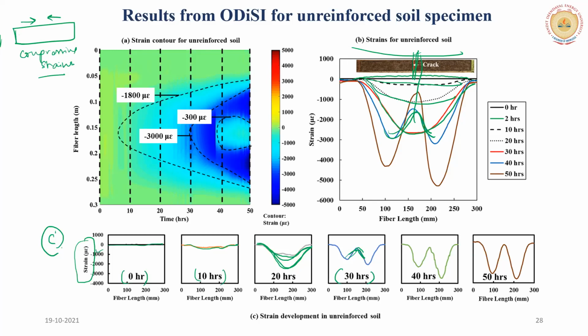For this kind of case, you can do some re-wetting of the soil layer, or you can take different steps. Or if it is an application like slope stability, you can give an alarm to the residents of that area that this may fail soon, just like we use satellite images to detect any kind of damage, right?